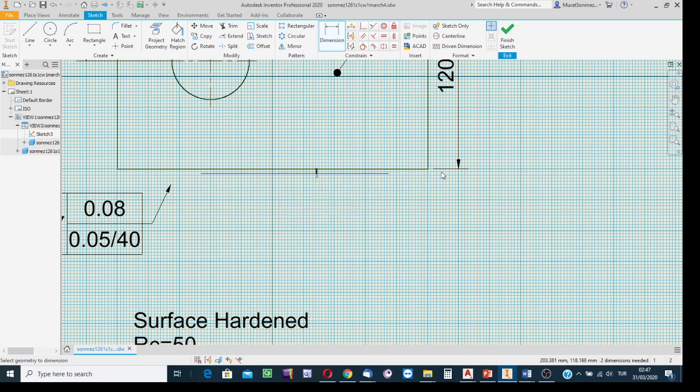And the other constraint relative to this boundary in our example, from here click to the terminal point. The dimensional constraint in this example is 30 millimeters. Write 30, press enter. Then indicate the line at a point and move the cursor away. It is to input the length for the chain line. In this example, for the portion of the surface, its width is 120. We have a technical requirement to satisfy. Write 120 into this sizing box, and then either click this button or simply press enter to input it.